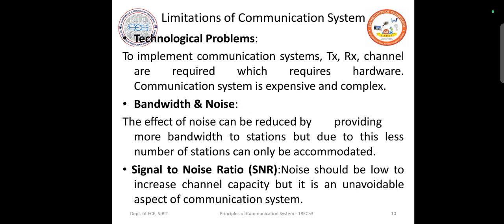Whenever I'm talking about bandwidth, we allocate certain center frequencies and give a certain band of frequencies to each channel. If you have to increase the number of channels, you will have to reduce the bandwidth. If you are reducing the bandwidth, obviously noise creeps in. So there is always a trade-off between the bandwidth and the noise. Noise doesn't mean that some external signal comes in and adds to the signal. It could also be a useful signal present next to the actual signal, which will create an interference, and that also becomes noise.